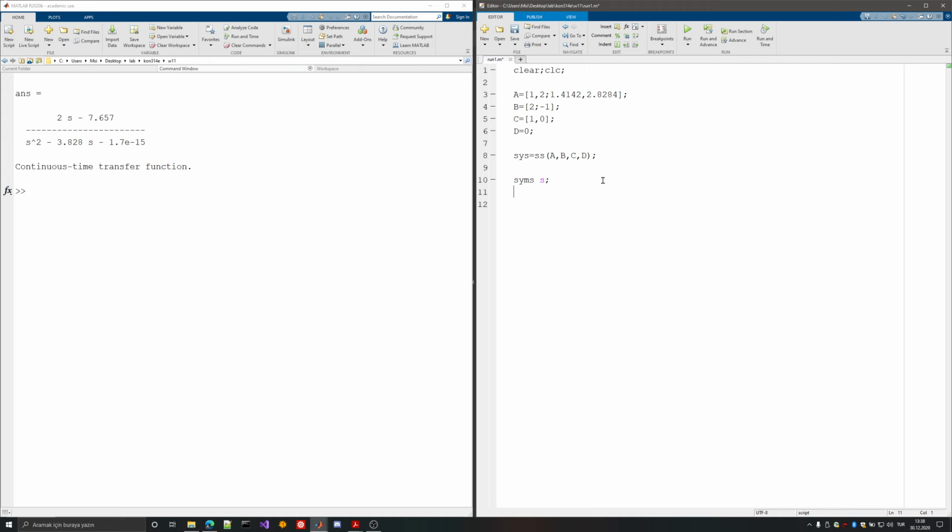Now, since x dot equals Ax plus Bu, this is our first equation. I need to take the Laplace transform here, since at the end I want to end up with a fraction of polynomials of s, and s is the Laplace variable. So I can use this differential equation and transform it into the Laplace domain.